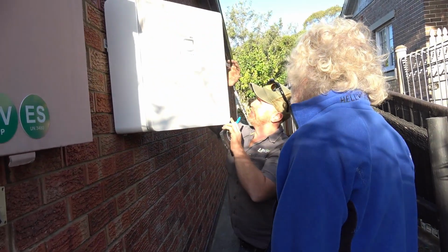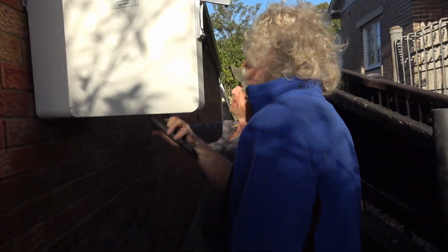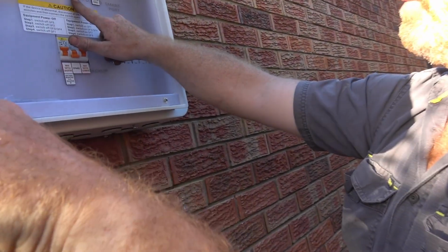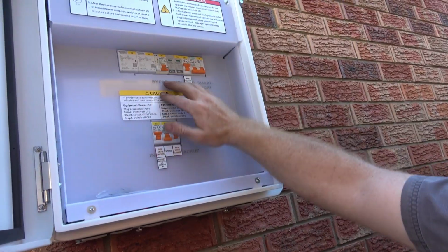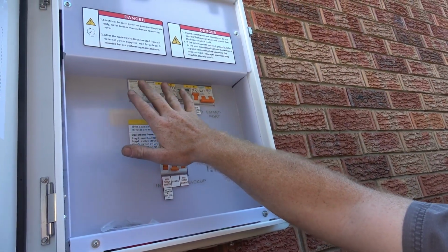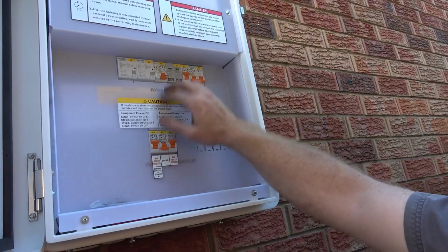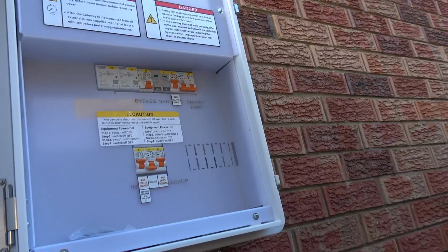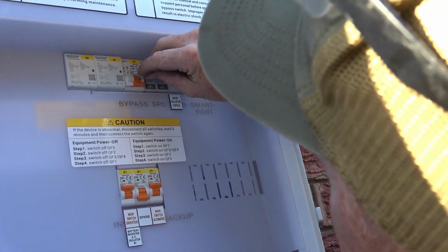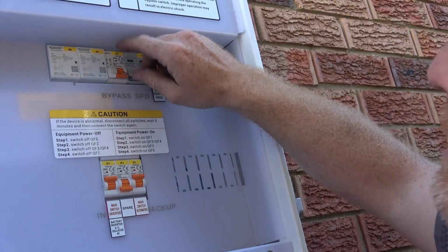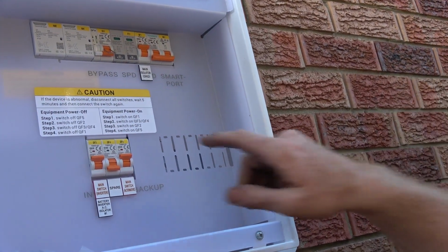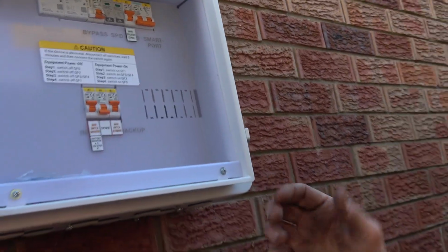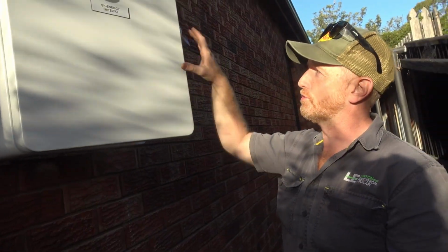Not much to know in here. There is a bypass switch here. Let's just say 10 years from now, or 7 years from now, something like that, one of these two contactors, the power for the house runs through these contactors, let's just say one of them failed. You can take out this pin, turn on the bypass switch, and then it will get the power back onto your house. It doesn't disconnect the inverter and battery, it just bypasses this contactor. The off-grid mode probably won't work in that scenario, but if something like that happens, you're just going to call us anyway.